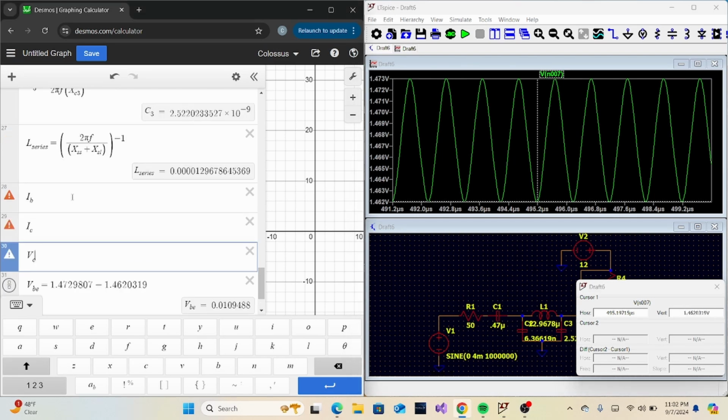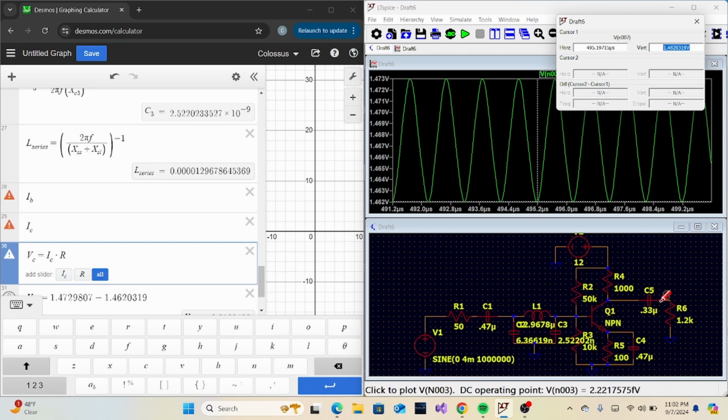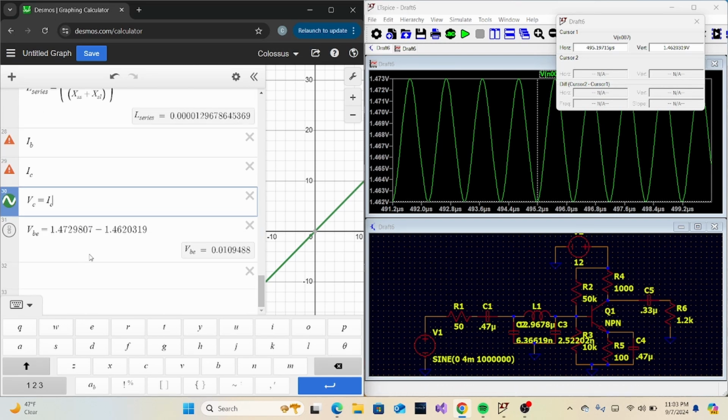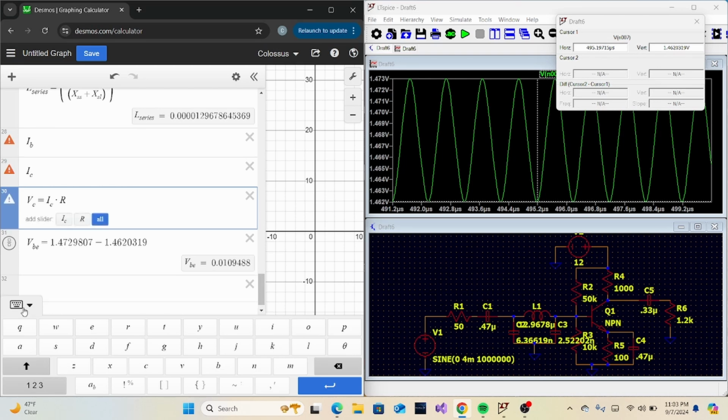We're going to try to solve it and then see if we are right or not. All right. So VC will always equal I sub C, the small signal collector current, times the resistance of the output. This is going to be the parallel combination, from here to ground through this shorted power supply. We're talking about AC, so we need to short this. Now what do we see looking out from the circuit? We see this in parallel with this. So we need to come up with a value for R out.